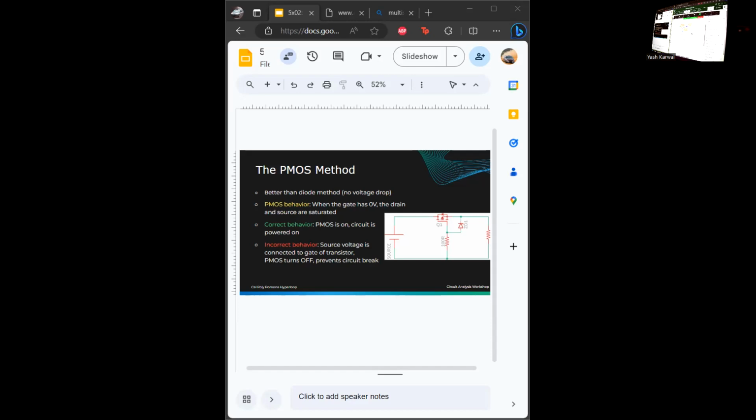So now let's run it. Right? The LED light is on because this gate right here is touching the ground, right? It's directly connected to the ground. So 0 volt is always going to be shooting into that gate. Which means that since this is a PMOS, it allows voltage to go through, current to go through, right? So that's why we have that drop, and then we have the LED light turning on.